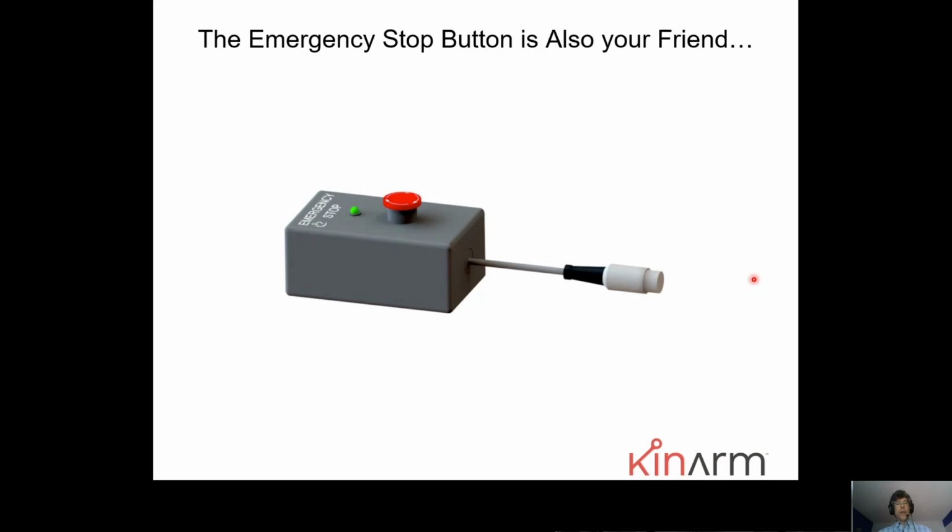If you are testing out loads, the other thing I'll mention is, particularly with the exoskeleton, never test it without somebody actually in the robot. Our robots are quite light and it doesn't take a whole lot of force for those robots to be accelerated and move at a very high speed. Easy for you to overcome if you're actually in the robot, not so easy if you're not in the robot. So always make sure that someone's in the exoskeleton when you're testing out loading conditions.